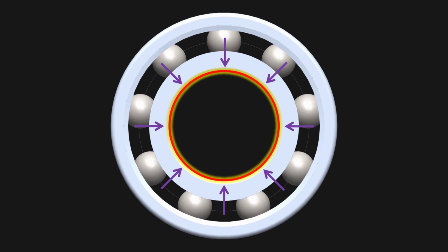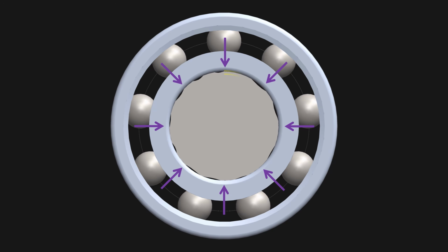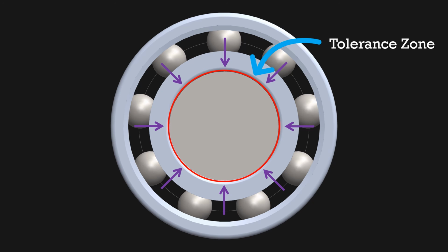So the shaft OD, the mounting shaft OD, should be maintained within the tolerance zone, but should also be precisely circular in shape. So the bearing ID and the mounting shaft OD will touch and support from all around. So here we must define the circularity control over the bearing mounting shaft.